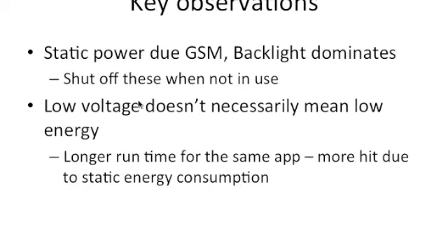What happens is when they reduce the frequency, they also have the ability to reduce the voltage. So that not only reduces power, that also reduces the energy. But if I have a certain application, a certain program I want to run, like say the earthquake program, which has so many million instructions, when I reduce the frequency, it just takes longer for the program to finish because it's running slower.